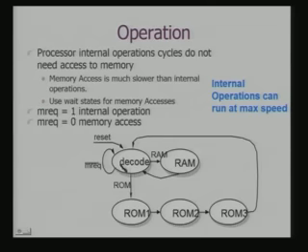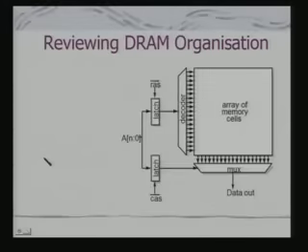So, when it is M request 0, I go to the RAM, decode, and come back, and when I am doing the access here, it is a ROM access, and corresponding to that there will be the wait state which would be generated. So, this M request signal indicates at what point the wait should really be made active when we are doing a ROM access.